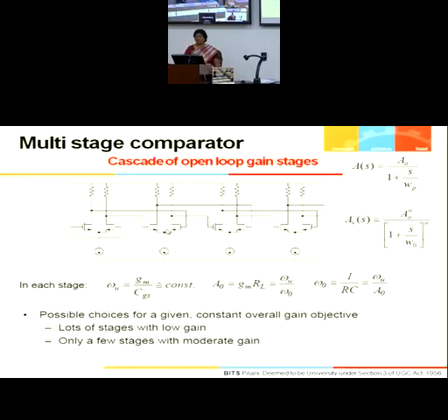That will be the multiplication of the transfer functions of n stages taken together, that means this factor to be multiplied with the same function n times. So this A naught will become A naught to the power n, and 1 plus S upon omega P will also have a power n. This will be the transfer function for this n series cascade.